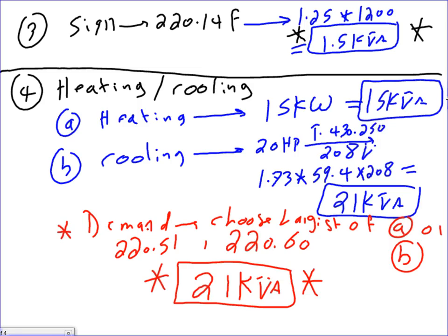What is 220.51? I can't remember it. What does it say? Fixed electric space heating: 100% of the total connected load. Yes. And the 220.51 should really be right here, so technically you don't need it here. And for cooling, you're going to go to Article 430 because it's a motor. All Article 430. So that's how they should be in terms of code.